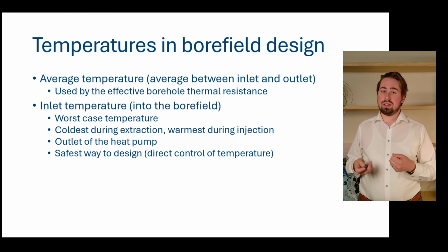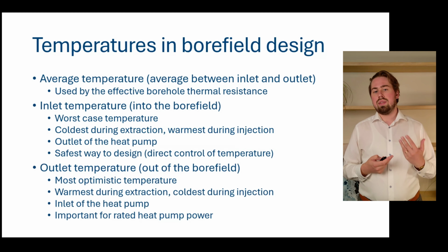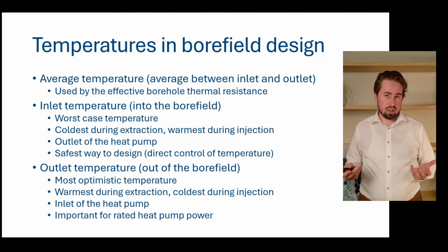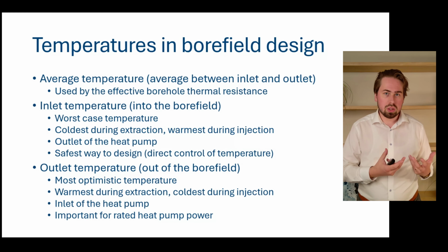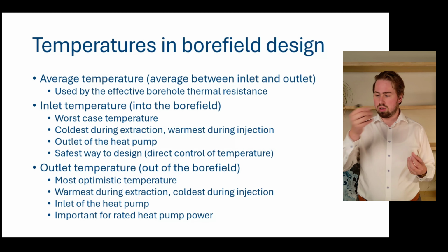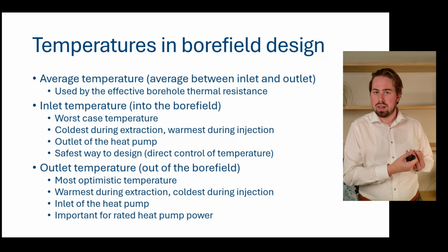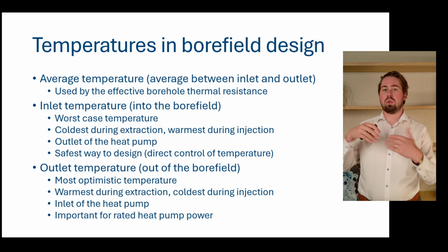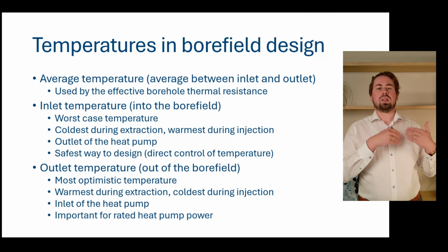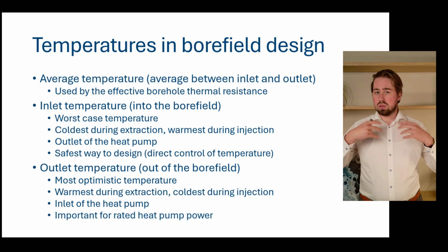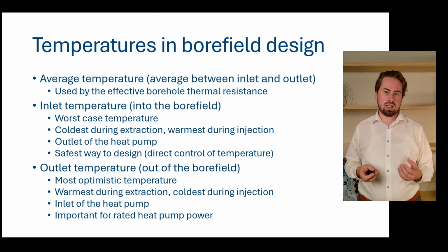On the other hand, you also have the outlet temperature, the temperature coming out of the borefield. And this is then what you can call the best case temperature, because it's always the warmest when you're extracting heat, because your cold fluid goes into the ground, heats up again, and it comes back warmer. And the same when you're cooling with your system, your warm fluid gets into the borefield, it gives away part of its heat, and it will return colder. So the temperatures coming out of your borefield are always the best case situation, let's say.